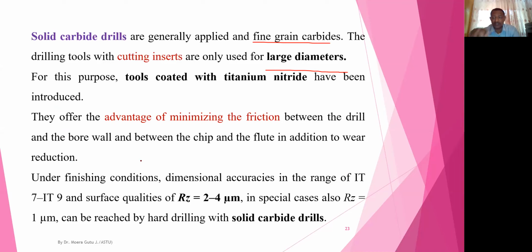The friction imposed during machining, because the twisting or revolving drill bits can produce high temperature, and high tool wear can be produced. So to reduce high tool wear of the cutting tool, the friction coefficient or the friction force should be reduced. For that, coated titanium nitrides are very useful because coating can reduce the friction resistance of a material.